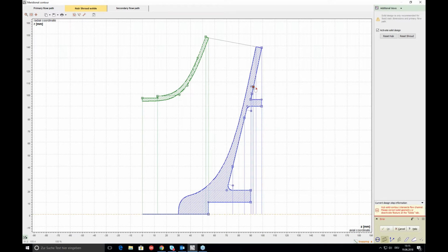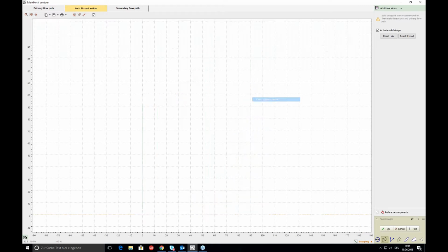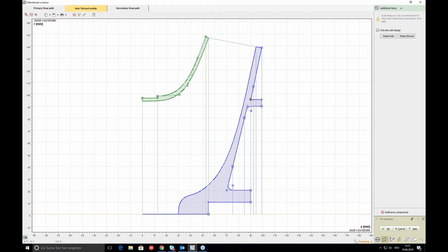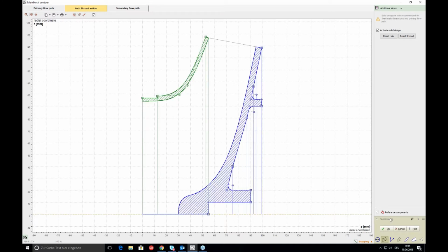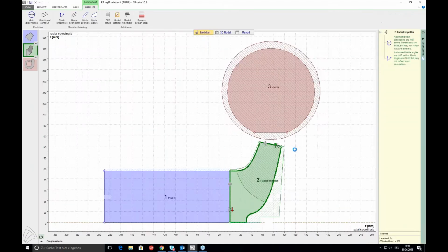That was too much. I'm using the undo feature, and the control point is gone again. So what I want to do here is make it a line segment. This is already one. Merge this again and apply a radius. Yes, and here we are very quickly. Maybe that could be a bit wider. Okay, anyway, that's going to be the one that should do it for the time being.